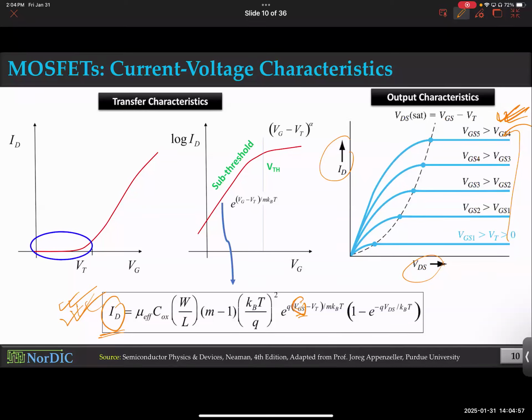And notice VGS is actually within an exponent. So e power VGS or something. There are other stuff, but VGS is a power of exponent. So that means current is exponentially dependent on VGS. So basically, drain current is even more responsive to VGS below threshold, which we have kind of ignored for the most part of electronic life cycle. Does that make sense, folks?